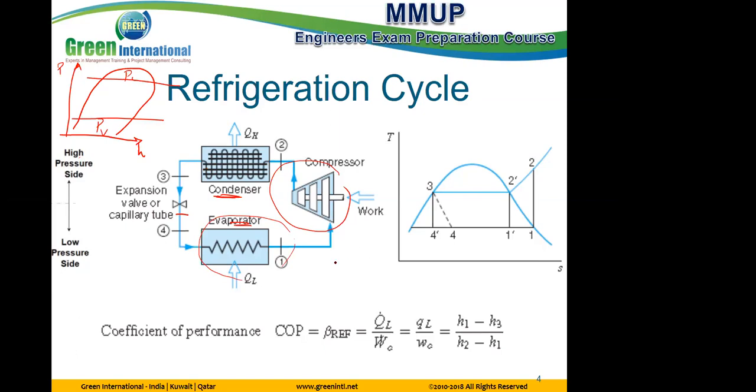The process is one going to the compressor and out at 2. So point 1 is at least totally superheated. Why? Because it's going to the compressor. Compressor is totally different from pumps. A pump needs totally water, but a compressor needs totally gas. So this is the point 1.